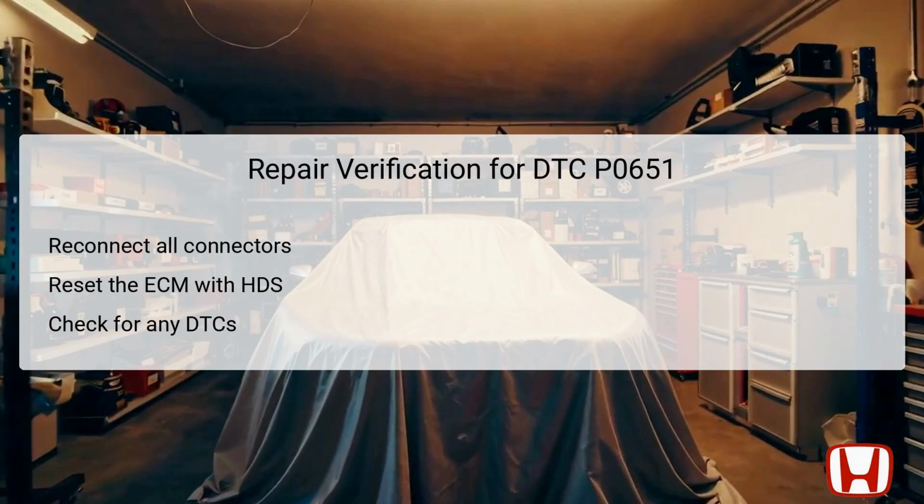Following the completion of repairs associated with DTC P0651, it's essential to conduct a verification process to ensure the issue has been resolved effectively. Start by turning the ignition switch to the lock position, and then carefully reconnect all previously disconnected connectors. After reconnecting components, turn the ignition switch to the on position to power the vehicle systems.